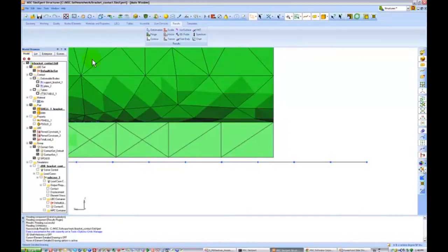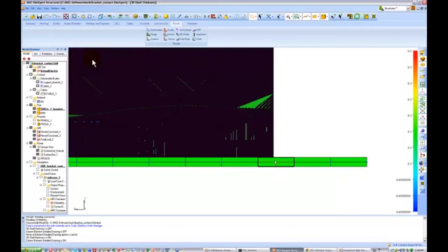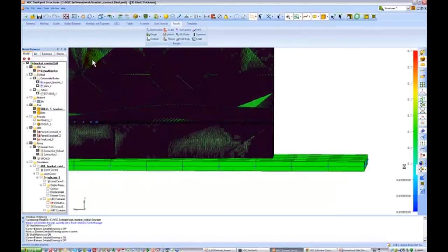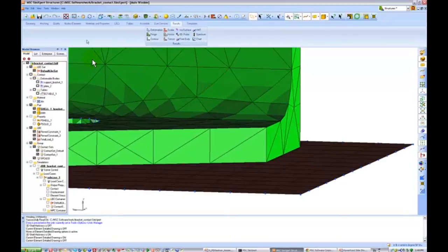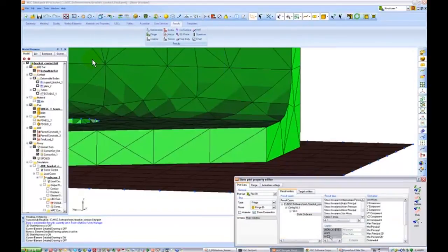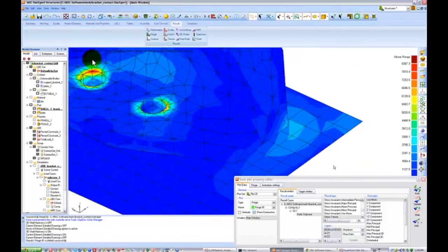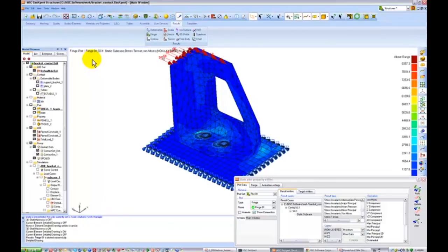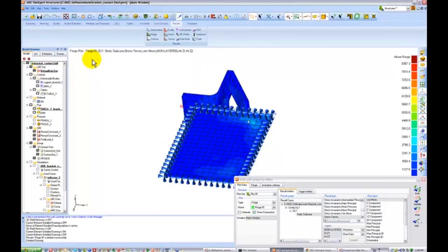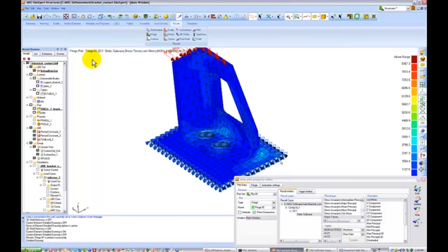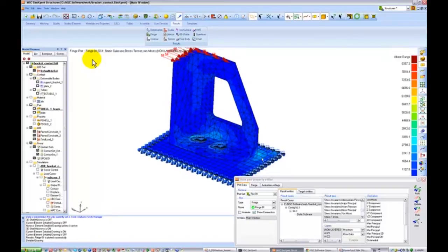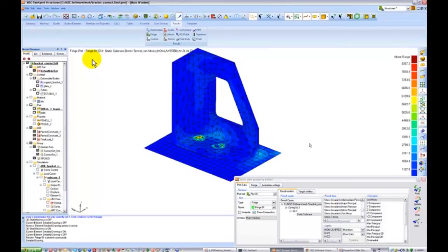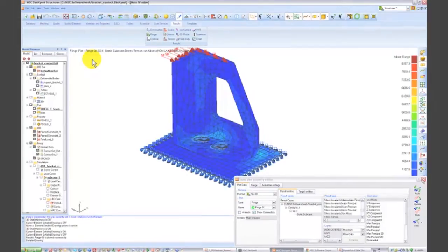If we show the shell thicknesses, we see that the total shell thickness is actually touching the solid. Once this is turned on and you solve for it, you can look at the results. Let's do a fringe plot of the stress, and we should be able to see that there's a heel and toe effect here. Essentially we're prying the bracket, applying a total load towards the minus Y direction, and we're prying and hitting the keeling effect on the toe of that bracket against the plate. This generates a very realistic load distribution, also in the fasteners, and then you can obviously perform more advanced studies with this. That's very rewarding in terms of simulation capability.